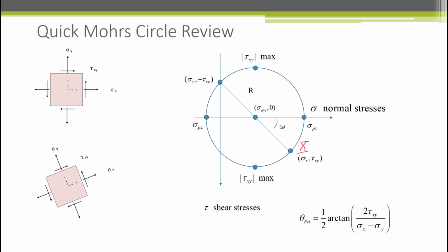Recall that the stress square element is like a limit in calculus. The stress element size gets smaller and smaller so that it can be used to approximate the properties at a point, which is infinitely small. Yet surprisingly, at least to me, direction matters for stresses even at a point of 0 size. For plane stress, we have at any point 3 independent stresses: 2 normal stresses, sigma x and sigma y, and 1 shear stress, tau xy, which all live on the perimeter of the Mohr circle.